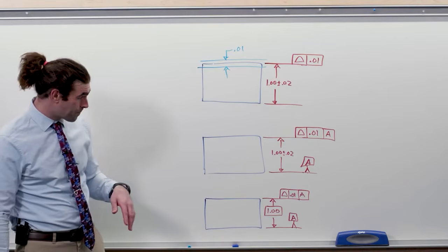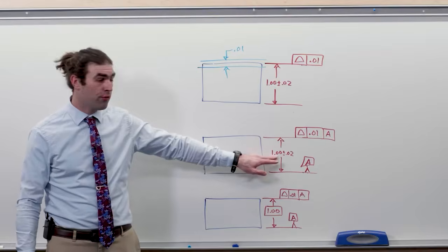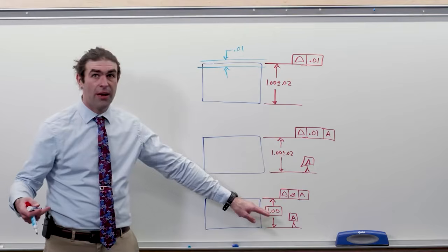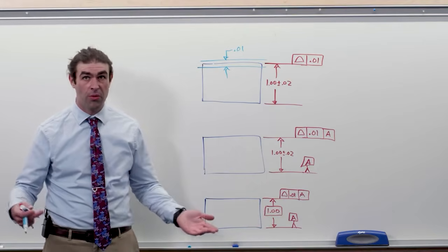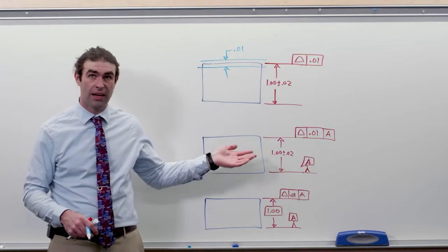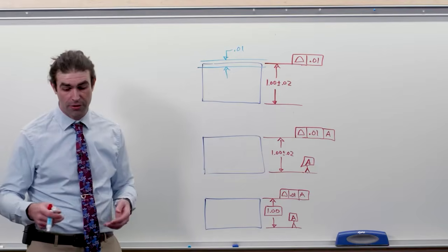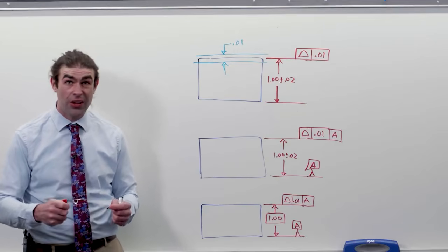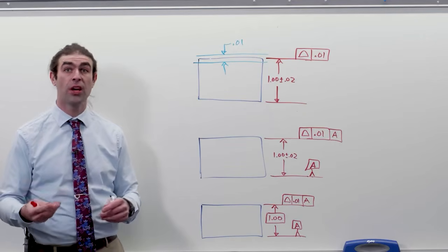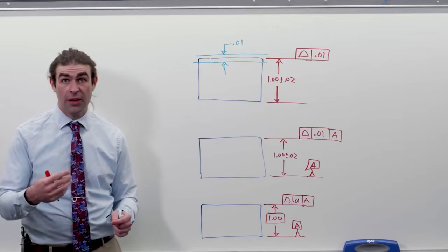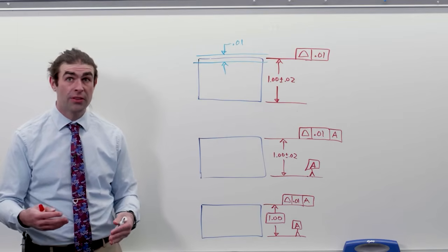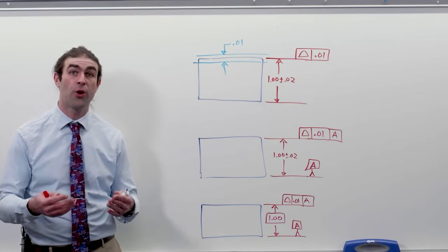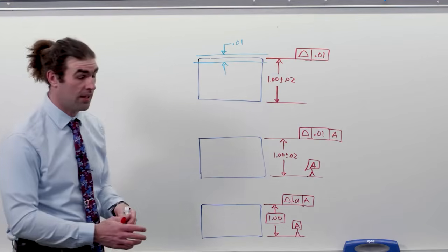We could essentially have a composite to 40 thousandths in the top segment and then do 10 thousandths just to A and essentially get the same thing as a plus or minus tolerance. I'll go over that in some other video. Now, profile also does something that none of the other tolerances do. It controls coplanarity. Now, in the ASME standard, it's clearly stated that even a profile with no datum references controls the coplanarity of surfaces. So what does that mean in this context?